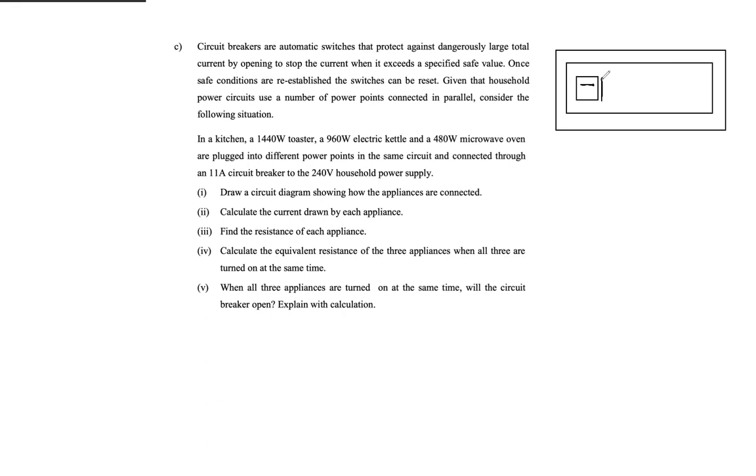After that you have the trip switch. That is, when there is a problem, if the trip switch falls down, the current in the entire household will stop. Sometimes when there's a problem in your electric equipment in the kitchen, like blenders or iron boxes, if they have an issue, then excess current is going to flow, and this trip switch will fall down. The main switch is not automatic. The trip switch is automatic. This is the main switch. This is the trip switch, and it is automatic.